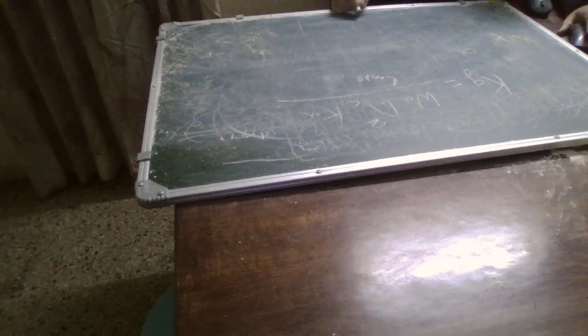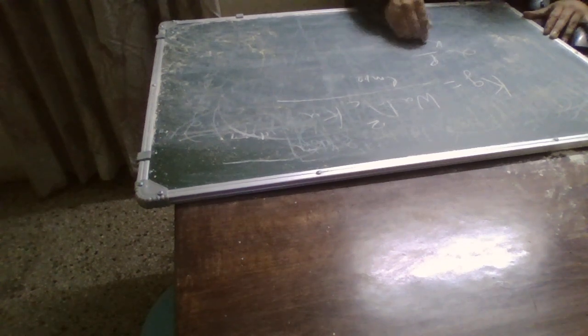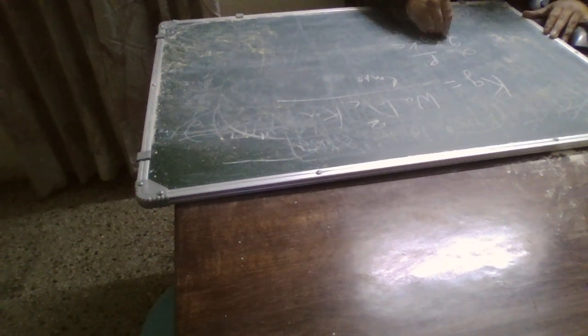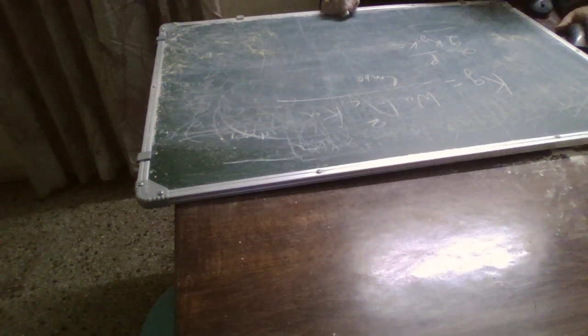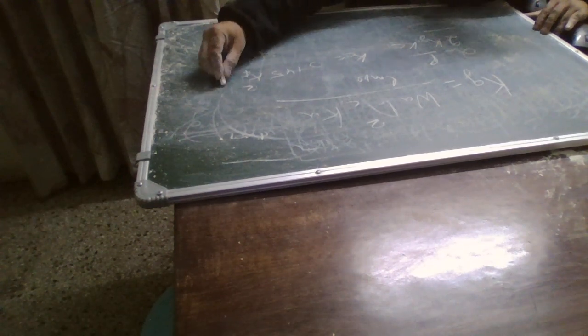Similarly, the other constant that I have taken in this alpha: one was Kg, the other I have taken is Ke, into one half of this. So this Ke is basically determined by the magnetic and the electric operating conditions, and here Ke is basically 0.145 Kf square, Kf square sorry, and the frequency square multiplied by this Bm square into 10 to the power minus 4. And again this Kf, I have said, is the waveform coefficient.